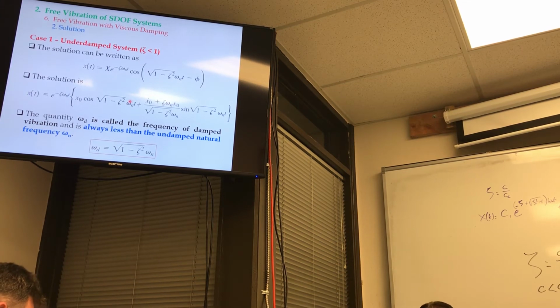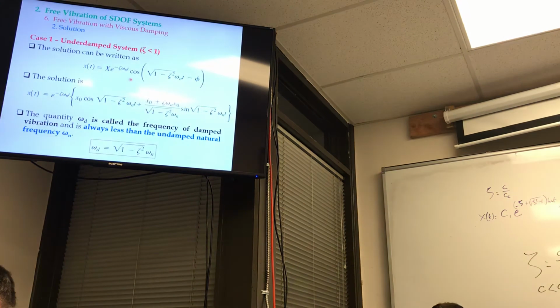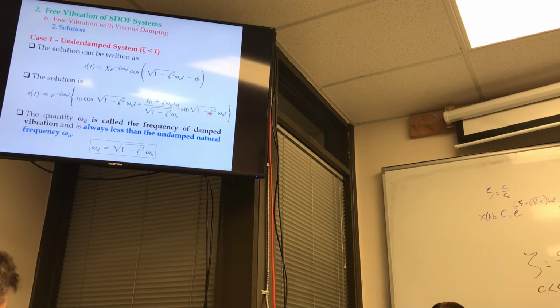That's pretty straightforward. You look at the equation, you can immediately tell. So in this case, when it's underdamped, the equation looks in general like this, but when you apply the initial conditions to it, it's going to look like that. So all you have to do is figure out what omega n is. And what is omega n equal to? Square root of k over m.